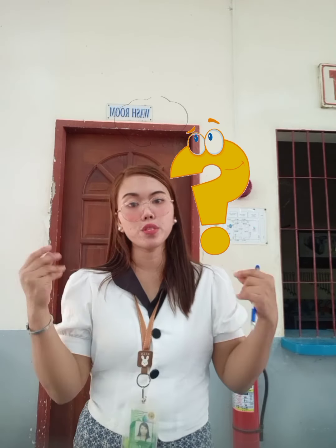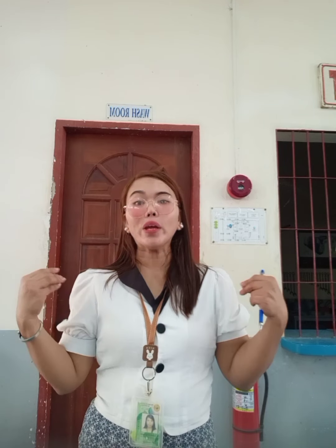Okay, the first thing you do while using the power hand tools, of course, you must wear your PPE, your personal protective equipment that is appropriate for the work you are doing, and safety glasses or safety goggles, or kung kailangan, face shield.